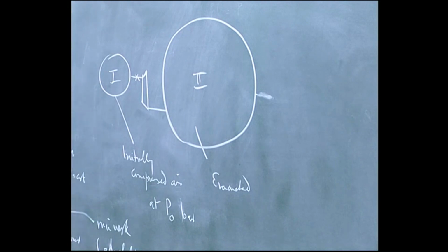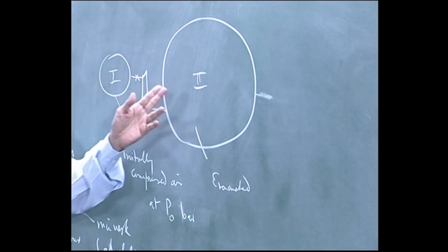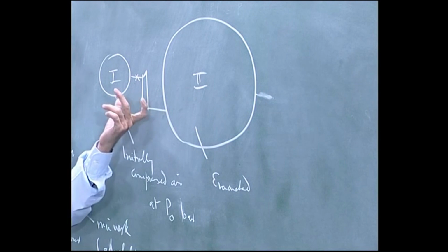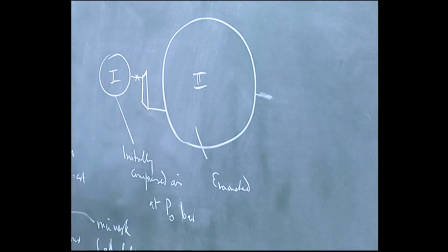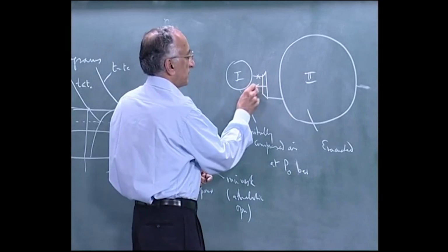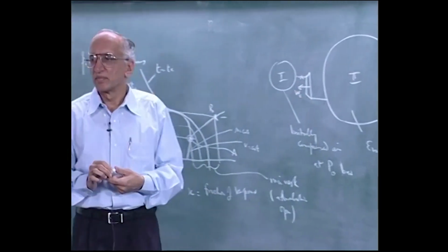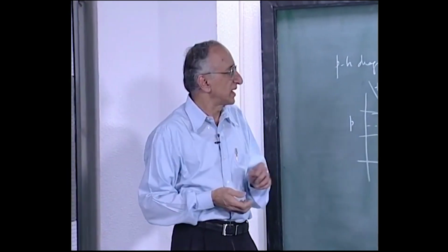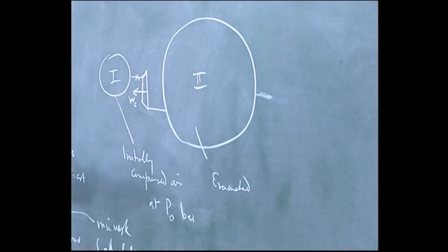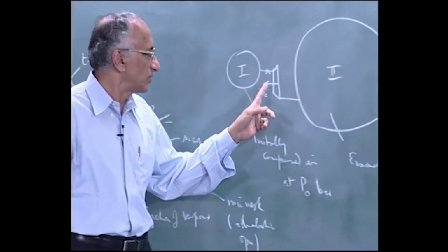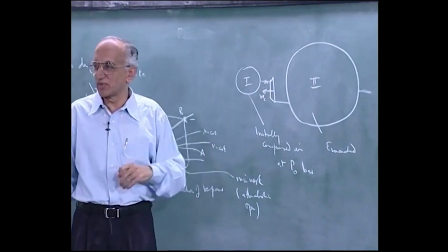Secondly, there are environmental considerations, whether the gas that you put in, if it is air it is okay, if you are taking some other gas for operations, you do not want to let it out into the sea. So what you do is pass it through an expansion engine, this engine will rotate, this will give you shaft work. So as the gas expands from one tank to the other, it turns a shaft which will do work for you. You may do minor repairs, you may take the hull of a ship and break up the crusts that are formed at some places and so on. Whatever the repair job that you are doing, you need an engine to help you produce work, and this is a typical device, this is carried on the back.